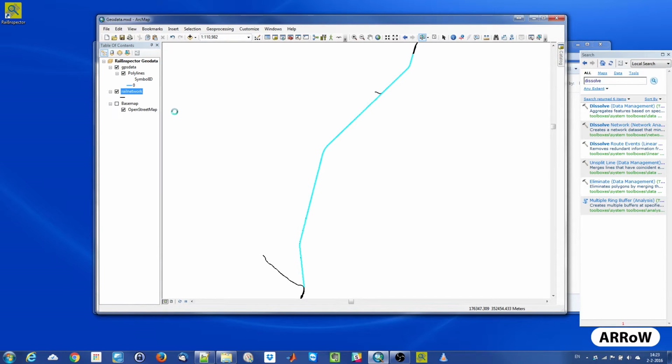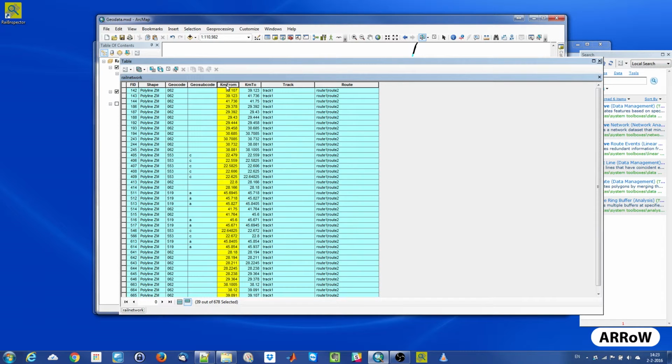So open the attribute table, I sort the kilometer field, and then I just check by hand if the kilometer 2 from a previous record equals the kilometer from the next record. You can check for yourself that this is the case for this. So after the merger, the kilometers will go on and there's no gap or something like that.